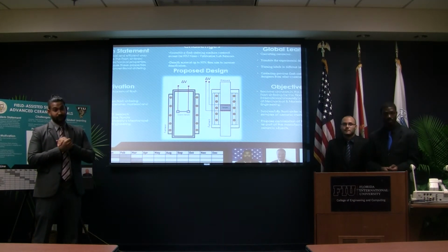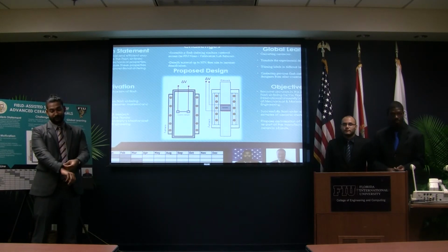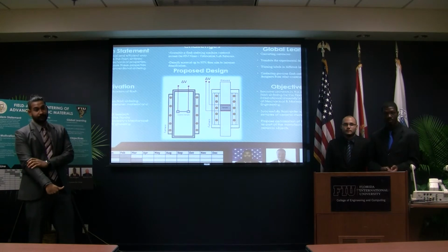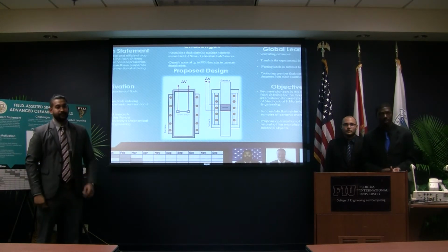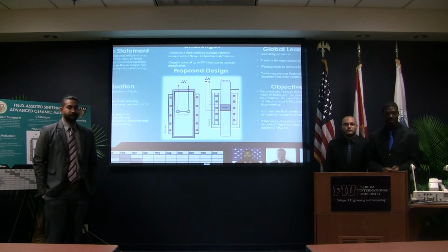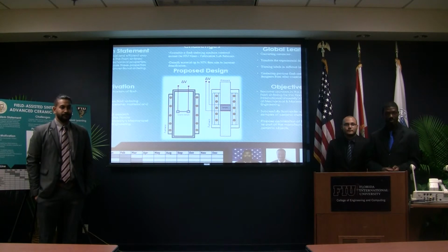Yeah, actually, it's funny because my doctoral dissertation work was on sintering ceramics. That wasn't the main thing, it was a byproduct, and I had to sinter it. It was old-fashioned school, a graphite furnace going to 2900 degrees C, and you had to ramp it up and stop for a while, and ramp it up and stop for a while.